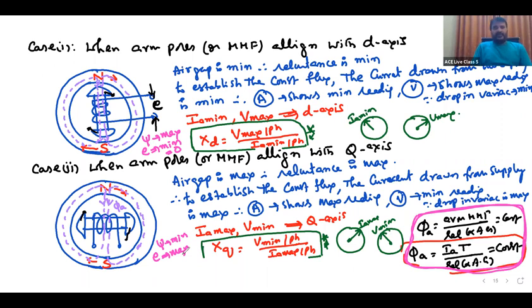It is not necessary to view that isometric view; I have already given it in the very beginning classes. At the time of the EMF equation I explained that if all the flux lines are passing inside of the coil, they do not cut. Simply the coil sides move parallel. So no flux lines are cutting and induced EMF is minimum. But in this case, induced EMF is maximum.